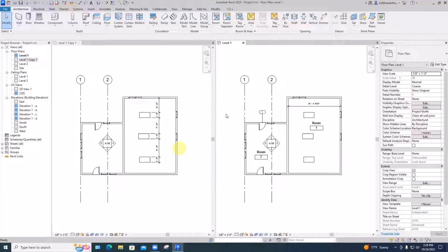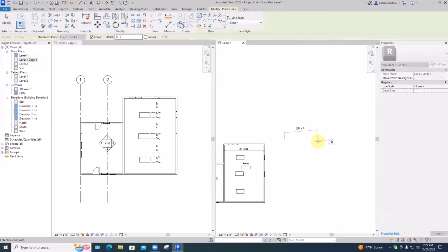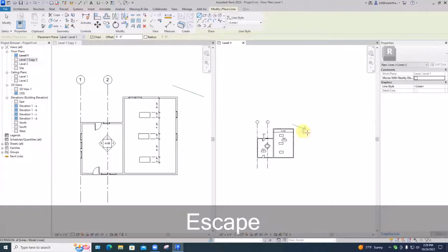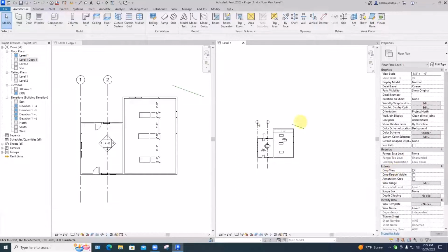Let's look at a couple of the drafting tools for a minute, because everything we do with lines, we can then start doing with walls, which are essentially, as Revit thinks of them, lines that have some width and volume associated with them. If I go into Architecture and decide to draw model lines, it stopped showing up because this view had its rectangular crop region turned on. I'll turn that off in this view.